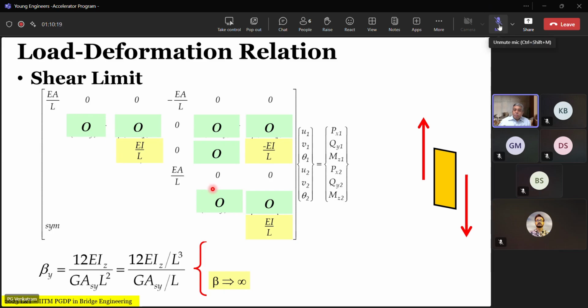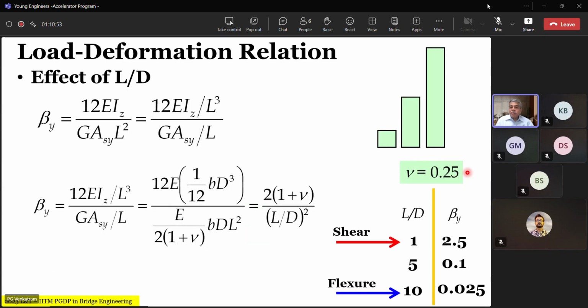Okay. So therefore, what does it mean? You don't go and discretize a linear member too finely by introducing so many nodes that you end up having very high shear deformation based control, and therefore you lead to an ill-conditioned matrix. Your results will be quite unreliable. So your discretization must also have a certain reasonable limit.